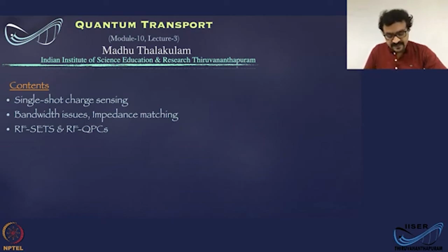What that means is you are sensing the electron in real time, and we will discuss the bandwidth issues and the impedance matching problem that has been faced by the conventional time average charge sensors. Those are the ones we discussed in the previous two lectures. And we also will discuss the basic technology of radio frequency single electron transistors and radio frequency quantum point contacts.